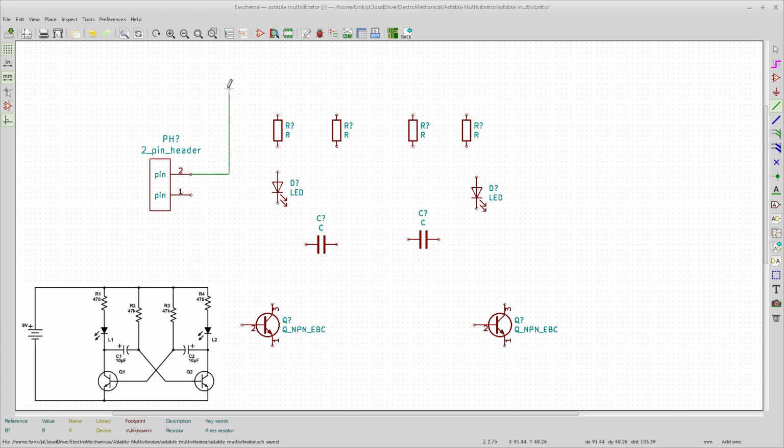So we'll go from here, and I do like this idea, come around like this and go here. Don't just wire straight across the top, okay? We get there, there, do. Make sure that when you do make a junction that it actually gets the junction on there, because I have had instances where it doesn't show up and it's actually not connected. You'll find that out in your electrical rules check later, right?